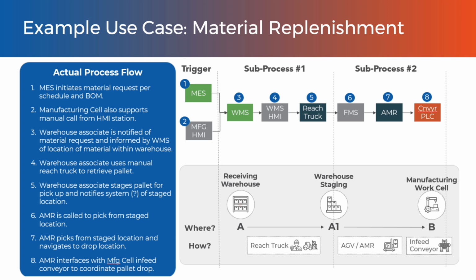But let's say that you also recognize that it doesn't work all the time. There's changeover concerns, maybe increased scrap. There's conditions where I want to be able to manually trigger this mission as well. And I want the operator to be able to do that themselves. So I need to access my HMI, my operator station, I need to add functionality in for the trigger. So we've got a second step here and a second system that we need to communicate with.